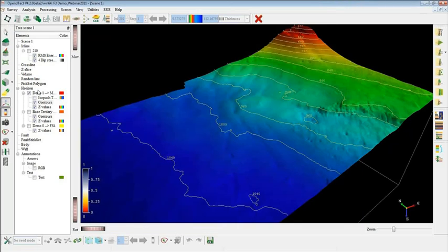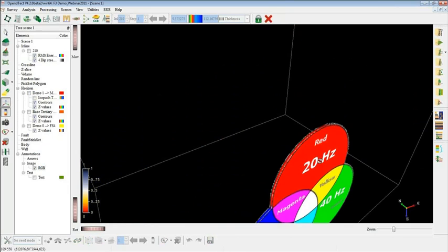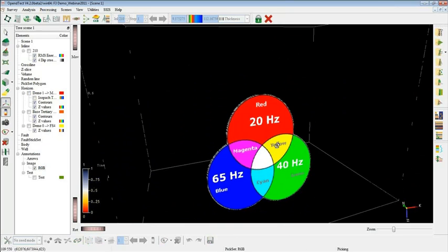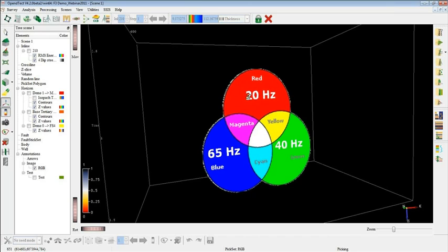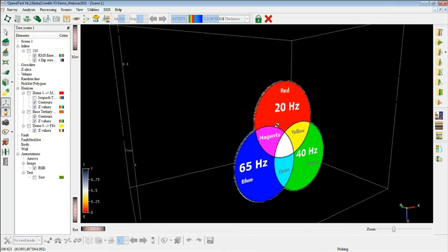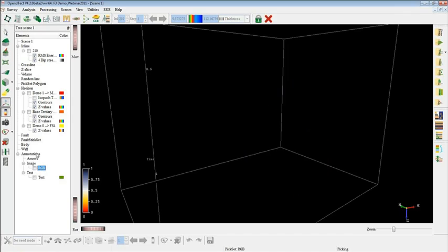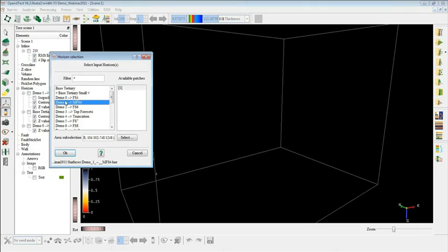So let's start with spectral decomposition first. As I said earlier, I need 3 spectral responses, and I'm going to blend them. So I need to load a color blended horizon first. How are you going to do that? You right click on the horizon and select load color blended, and you select the right horizon.